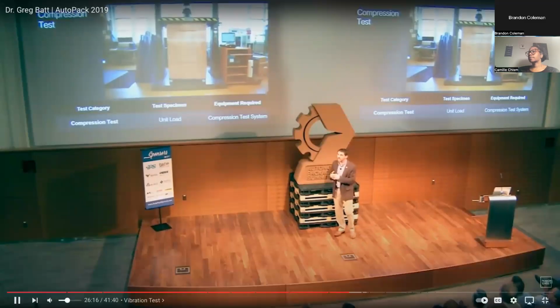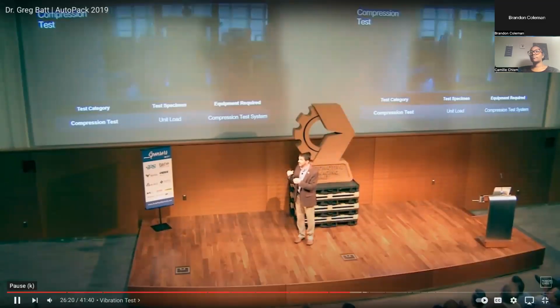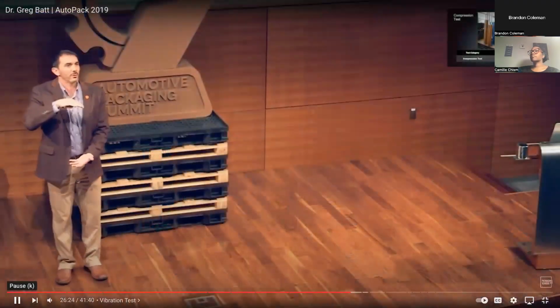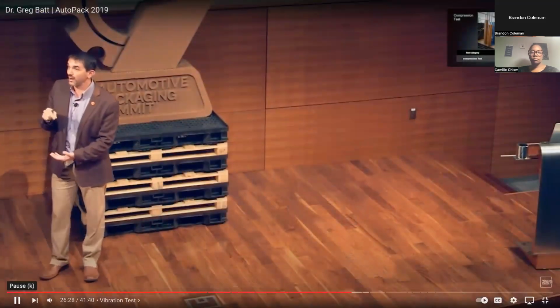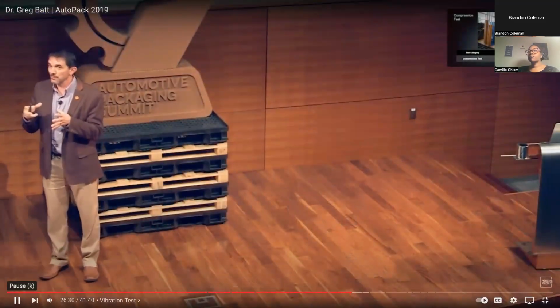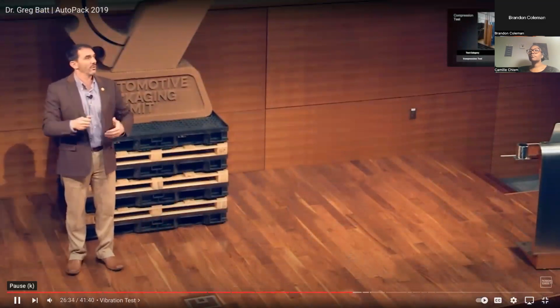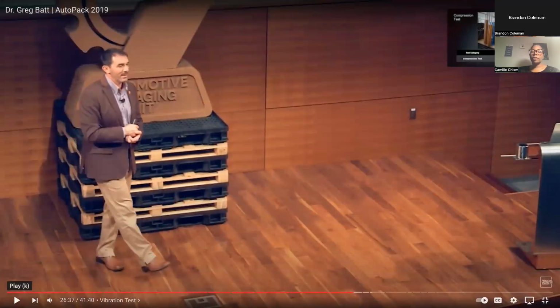The other approach, which I would consider more the engineering approach that we include in the development phase, is we're going to compress it until it fails. We want to know how much load our packaged product system together, where maybe our product can share in the load bearing, is able to support. That's more of what chapter 3 was talking about as far as test methodology.